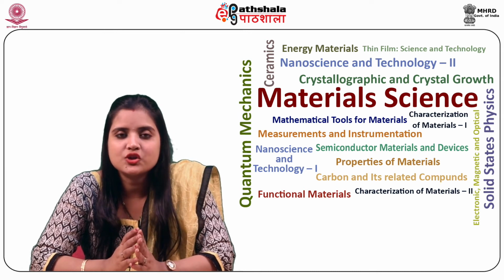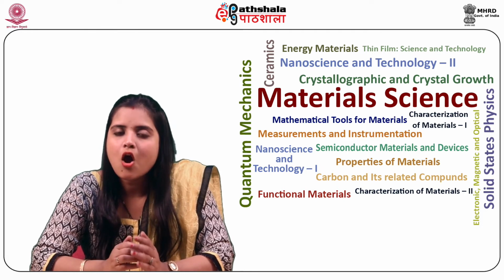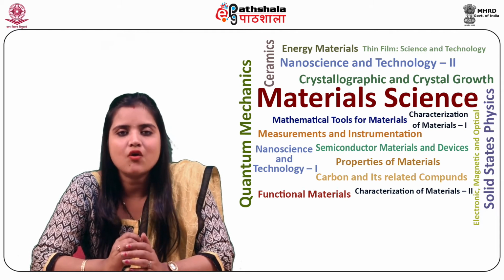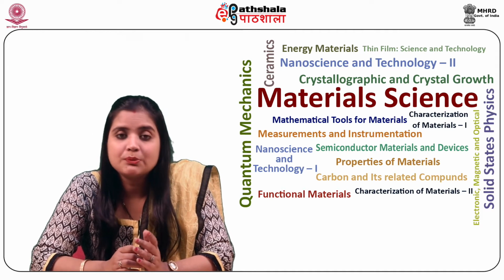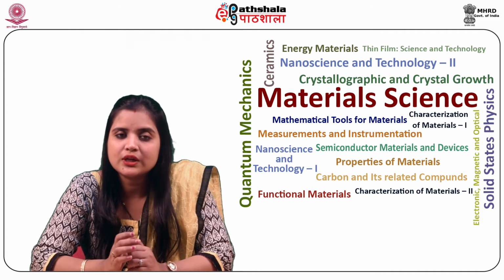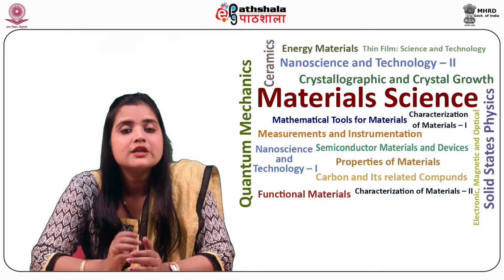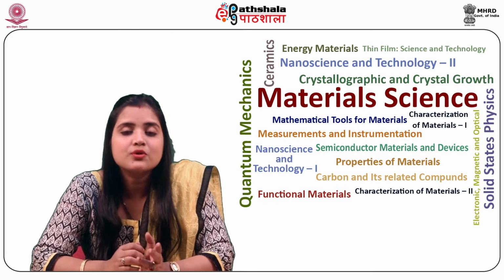The fabrication of integrated circuits consists of deposition and selective removal of a series of thin films. These thin films could be deposited using various deposition techniques including spin coating, vacuum evaporation, sputtering, vapor deposition, and dip coating.